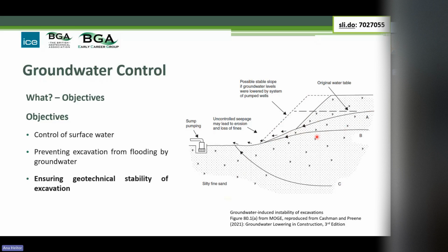But it gets worse than that. If you get down towards the bottom of the excavation, some of these flow lines in your flow net are coming almost vertically upwards. That implies that in the bottom of the excavation, you've got low total stress, high pore water pressures, you get nearly zero effective stress. And this condition known as quicksand or running sand will occur. And the excavation becomes so soft you can't even stand on it, and plant will sink in.